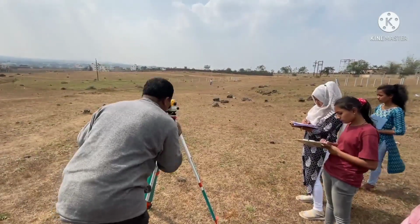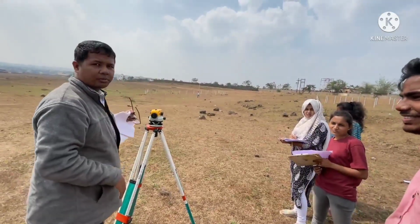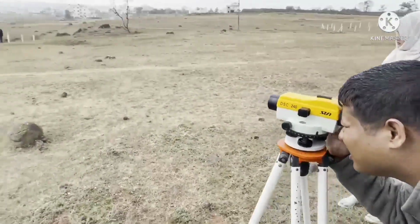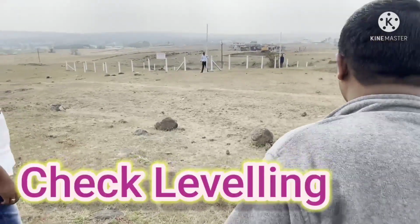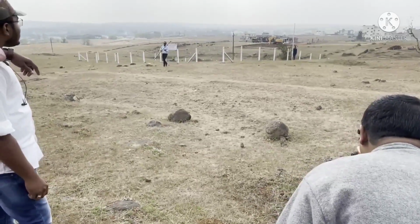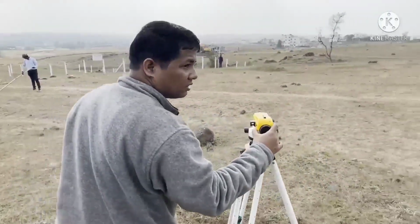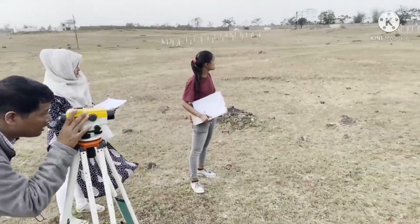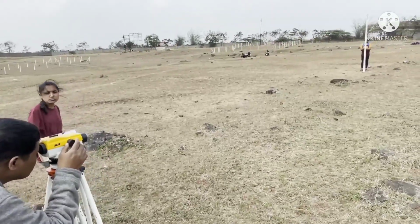So likewise we are supposed to go on taking the staff readings of each and every grid point. In this way we are going to conduct the staff reading. After taking the readings of all the grid points, we are going to carry out the check leveling process, that is nothing but from the end point. Suppose that was the last point, C100 R50. From that point we are going to do the check leveling, in which we check whatever work we have done with reference to the said TBM.